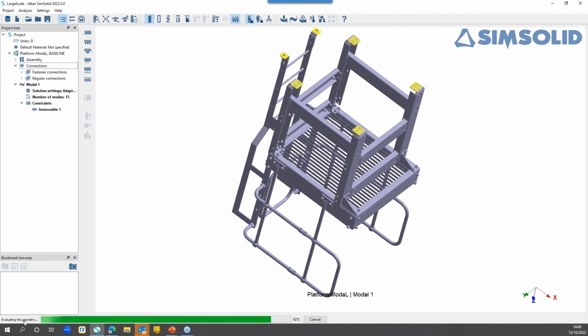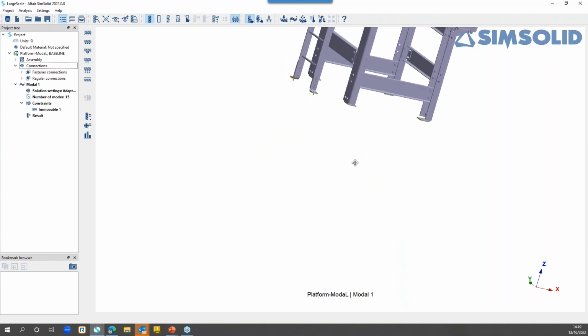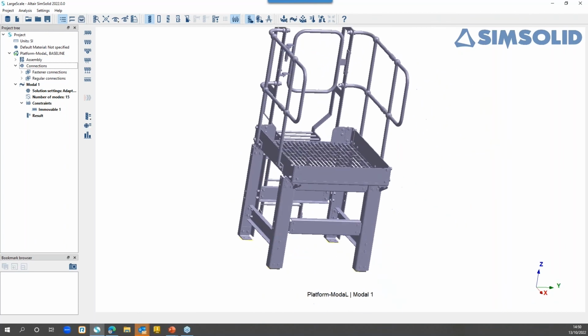At the bottom left-hand corner of my screen, I don't think you can see it, it goes through 3 iterations automatically by default. So it's going through 1, 2, and 3. So you could say it's going through a mesh convergence process itself. And how long do you think it would have taken if you managed to get that in Nastran and Inventor Stress? If you managed it, probably a long time. I think the biggest problem you're going to have is it doesn't mesh.